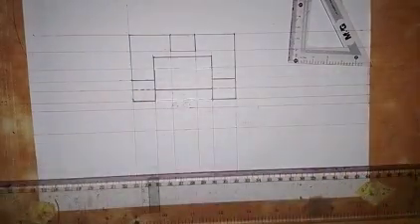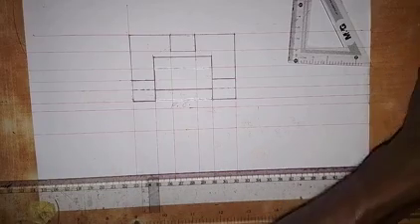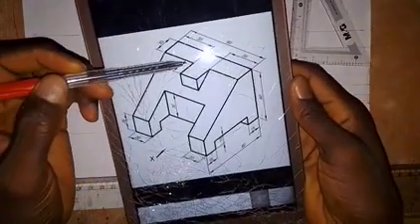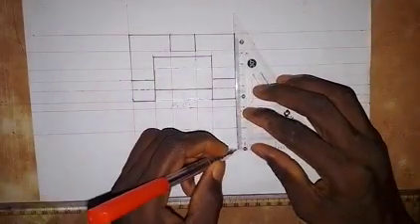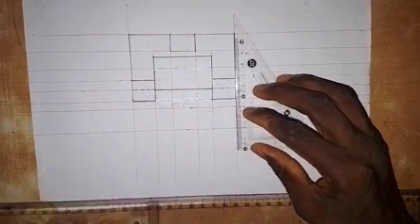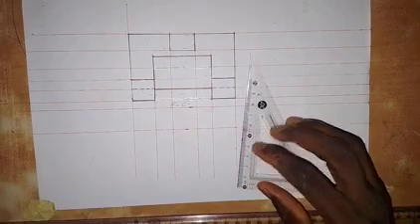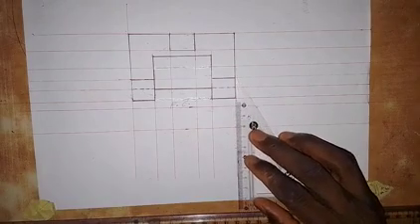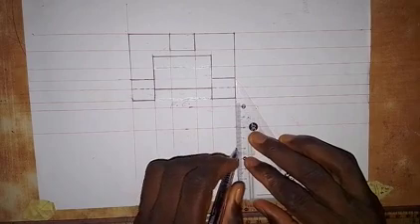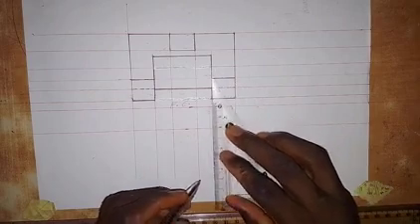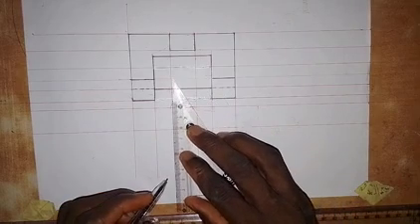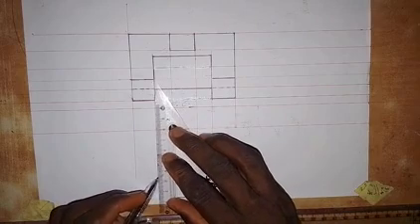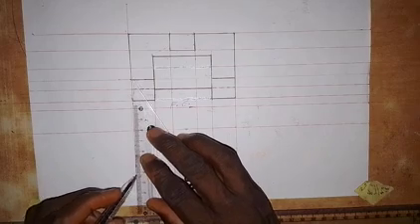There's another thing that we have here. The distance from here to here is also 20 millimeters. So I need to come down from here and take a measurement of 20 millimeters. So this is 20 millimeters here. I will need to extend this line because I still need 40 millimeters. So I will take this line down, and also this down, and this line down. Then I will take this line down, and also this one. And then we also have this.